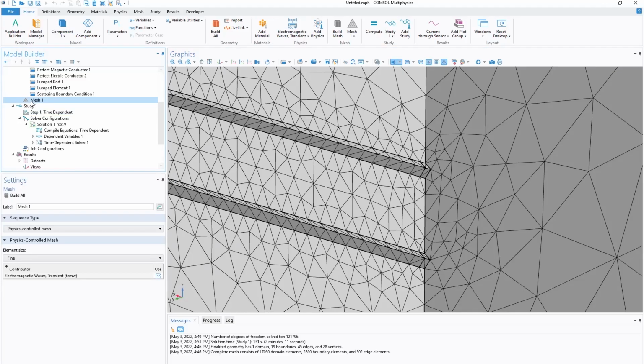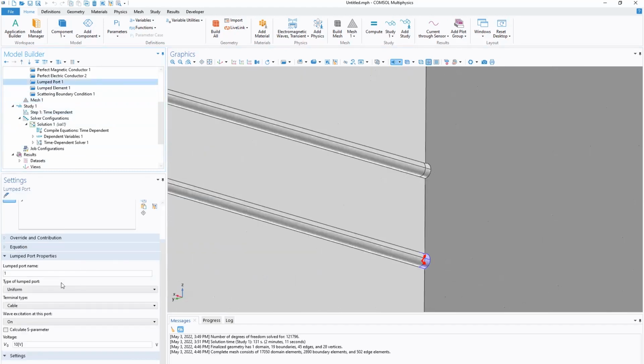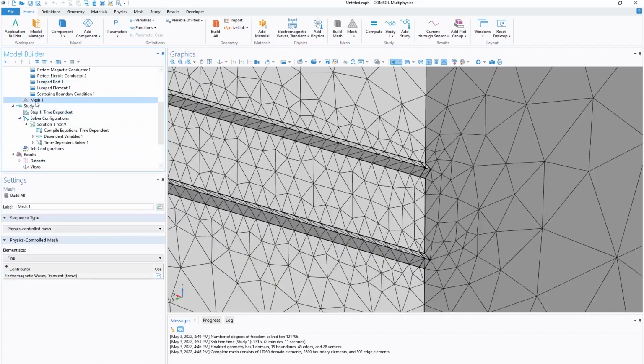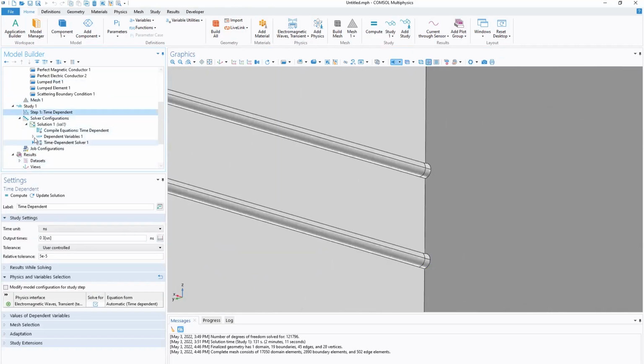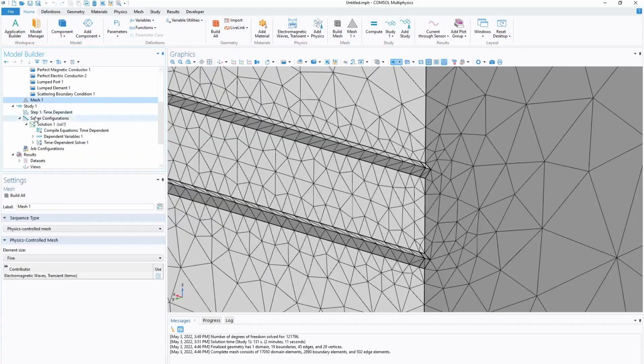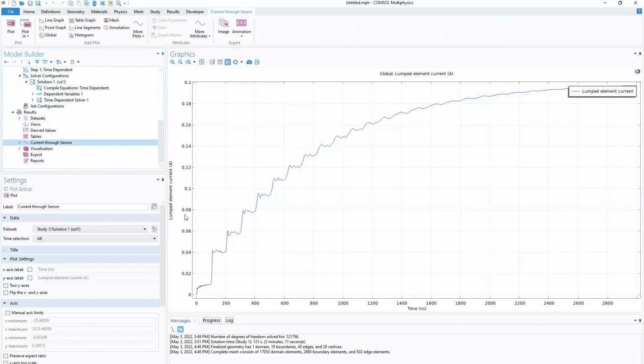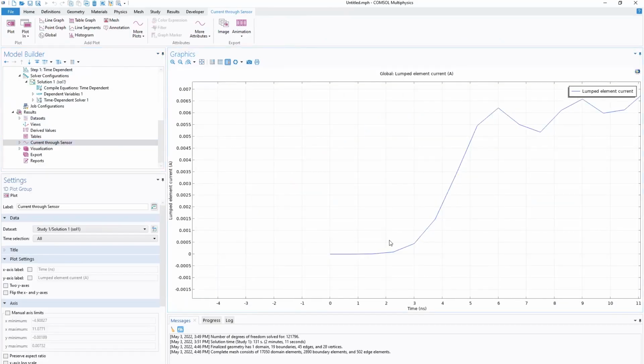And very roughly speaking, if you're familiar with the Nyquist criteria, you need to have, at a bare minimum, 2 elements per wavelength. So if we wanted to capture all of the infinite frequency content that exists in such an instantaneous change in the fields, we'd need both an infinitely fine mesh and an exceptionally fine tolerance. Obviously, we can't do that. So we have to accept that there's some numerical smoothing or numerical dispersion being added around that step change in the applied voltage across our source.